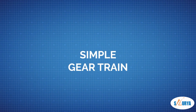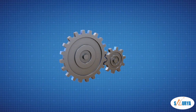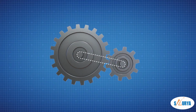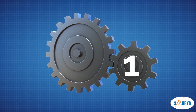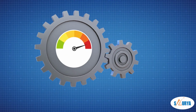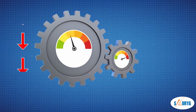Simple gear train. When there is only one gear on each shaft, it is known as simple gear train. When the distance between the shafts is small, it is used. When a small gear 1, figure 1, drives the bigger gear 2, the RPM of the bigger gear 2 is reduced in proportion to the gear teeth.